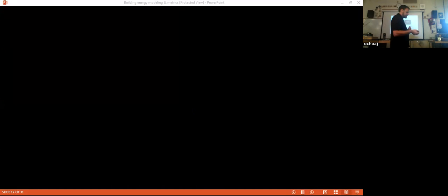You can be more detailed on the building and come up with different degrees of simplified BIM. I've made a few of these, and they're fairly detailed, but it's not something you're going to build on. It's an energy BIM. You have the building system parameters. And so what this is now, you take your simplified BIM and you add to that simplified BIM the equipment that's going to be in it. So what I would do is usually there's an equipment library.